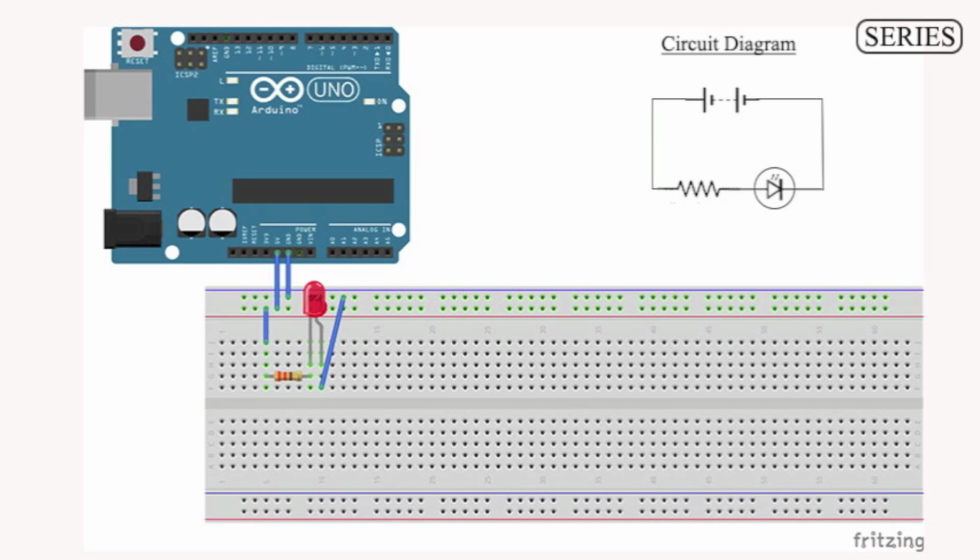To connect your components in series, ensure that only one end of the components is connected to another end of the components in the same bus. The free ends of each component will then connect themselves to different potentials for current to flow through both components. Now, let us visualize how the current will flow in the breadboard.